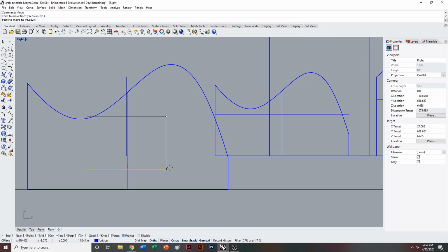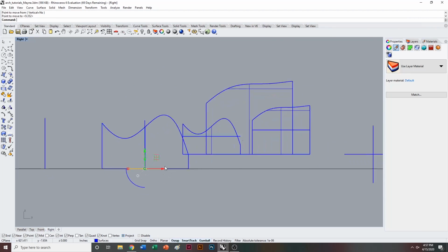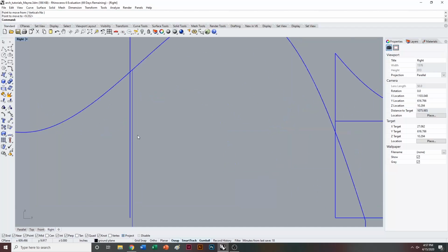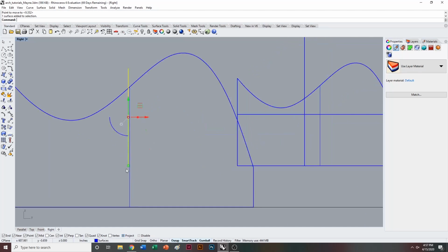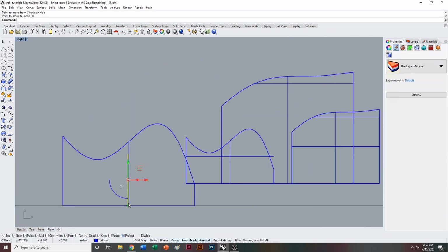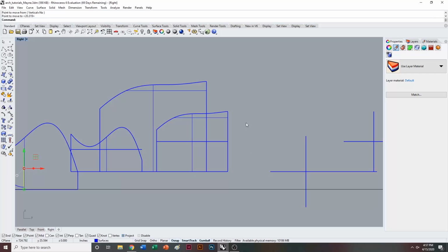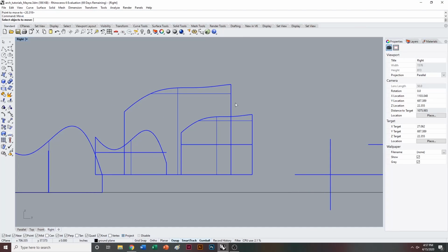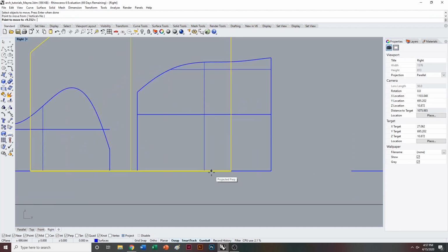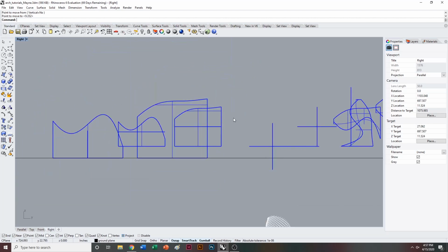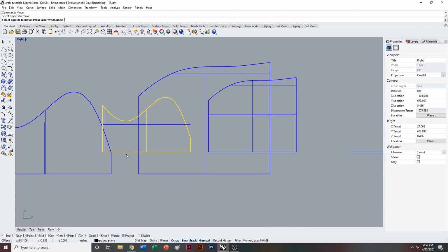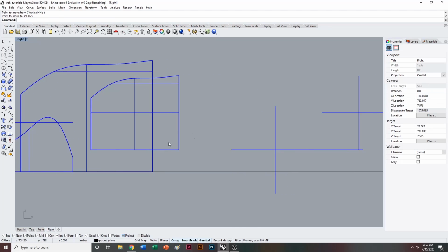If you have a really thin flat object like this, that's perfectly fine. We'll touch these up a little bit later, and same with these strictly vertical moments as well. And the way I'm redoing the command so quickly is if I type in move and then I select my object to move and move it down, once that command is over, if I right click, it'll rerun the same command that I just ran. So that's how I'm speeding through it so quickly.